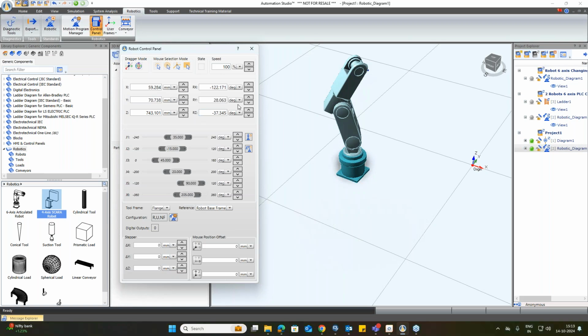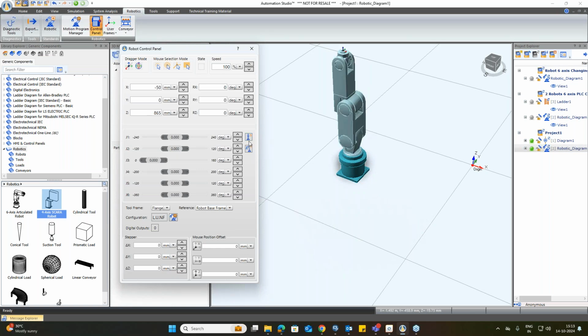If you want to use the Cartesian method, you can also edit your parameters using the Cartesian method. This will be edited with respect to your robot base. Again, there are two home buttons here. If you click on reset all robot joints, it will be reset to 0, 0. And there is another home button. It will put the robot in the user position.